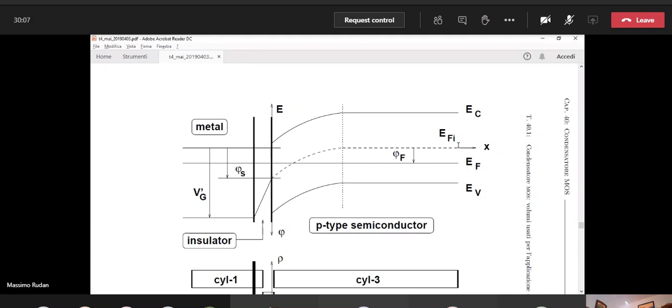That means that the electric potential inside the metal of the bulk contact, but outside of the semiconductor, differs by a constant with respect to the electric potential inside the semiconductor asymptotically to the right. Okay? So we have to account for the difference. It is easy. At some point we shall introduce this difference, but for the moment,